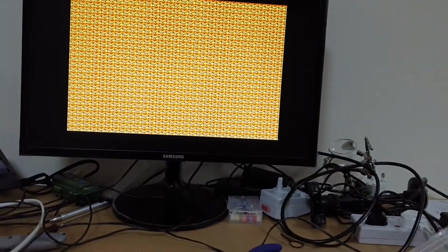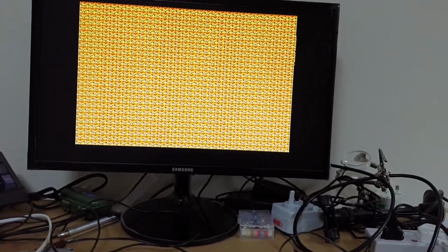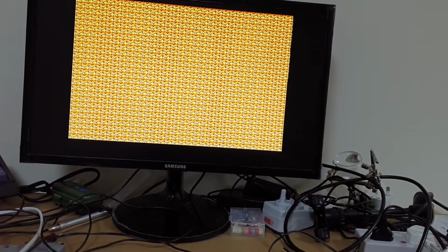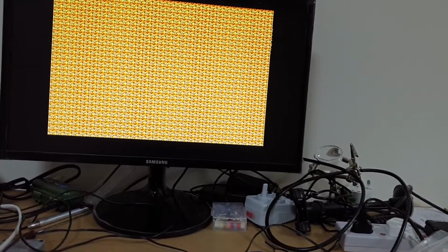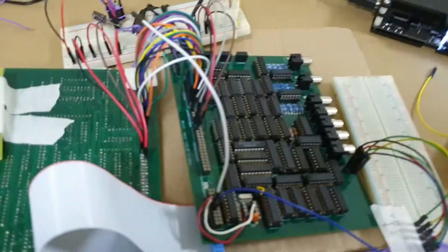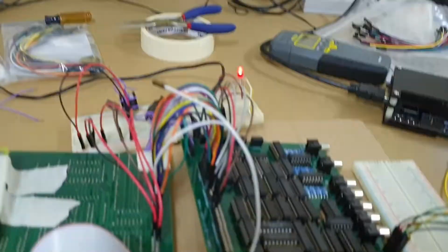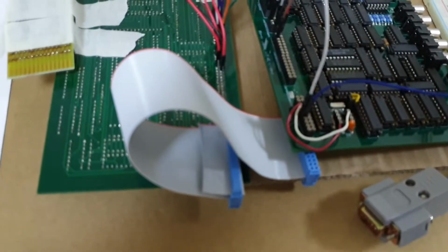So if I leave it alone, dangling, most of the interference goes away. But if I then grab hold of the insulation, it's come back again. So this gives a good indication that this circuit is especially sensitive with these long wires to potentially what looks like RF interference or some other analog electrical effect, which, I'm not an analog electrical engineer. I designed this PCB using my best effort, but relatively long wires, relatively long connections, which are a little bit unreliable.